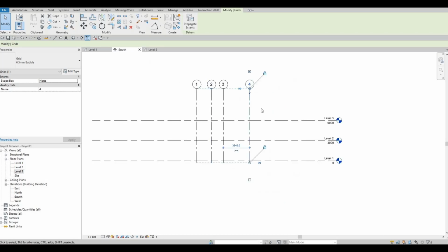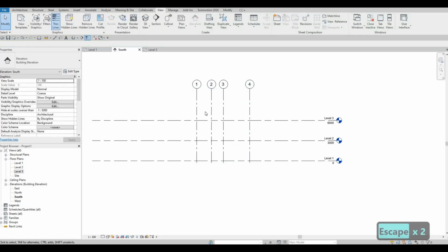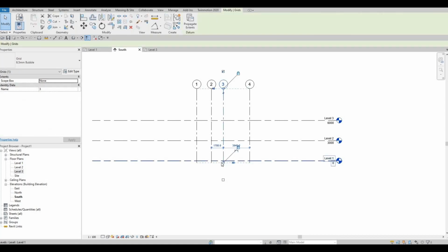So that's one of the issues if you don't see any grid lines on that level. So you want to make sure that everything is showing. Just extend it, and as you know, we have a temporary dash line here indicating that it's easy to pull it up or down because everything will follow.